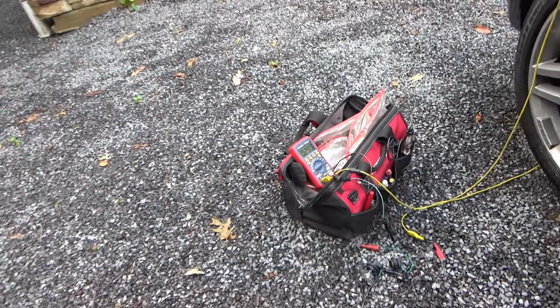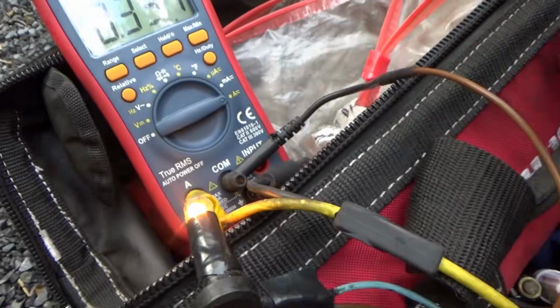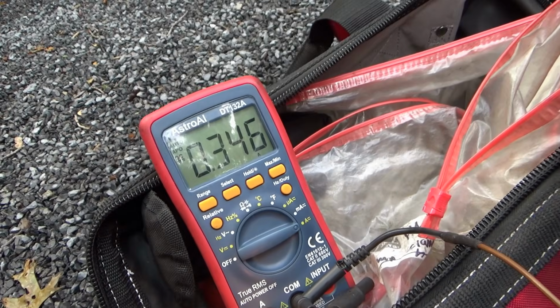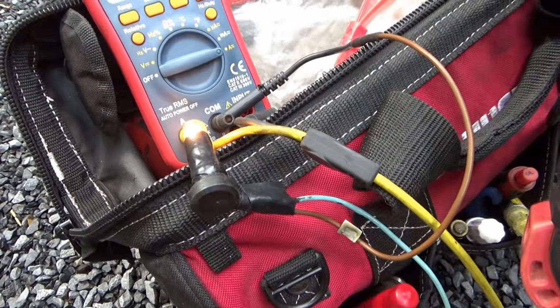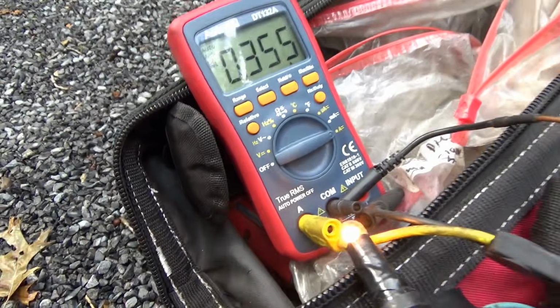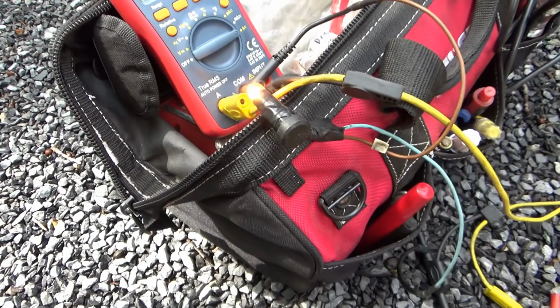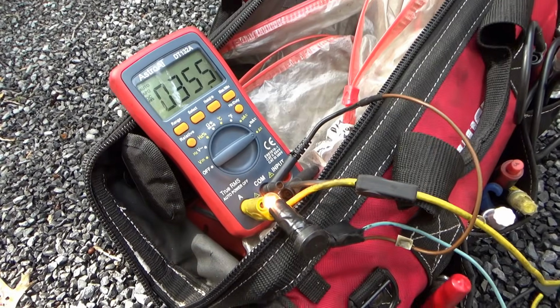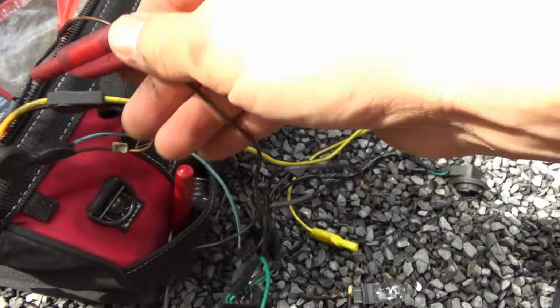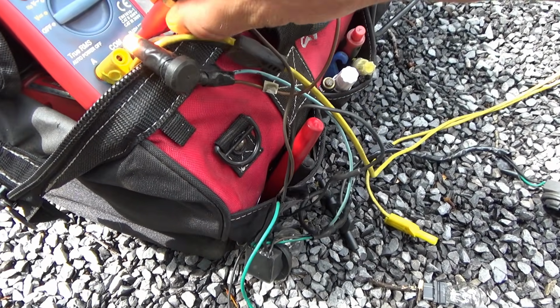Look at that. See, it's ramping up the amperage, and it ramped it up to 100%, so our test light's nice and bright. So that tells me the controller wiring is good, and it can carry at least 300 milliamps. So we can stress this circuit a little more. Remember, the compressor valve should draw about 1 amp. So let's add half an amp in parallel to this test light.